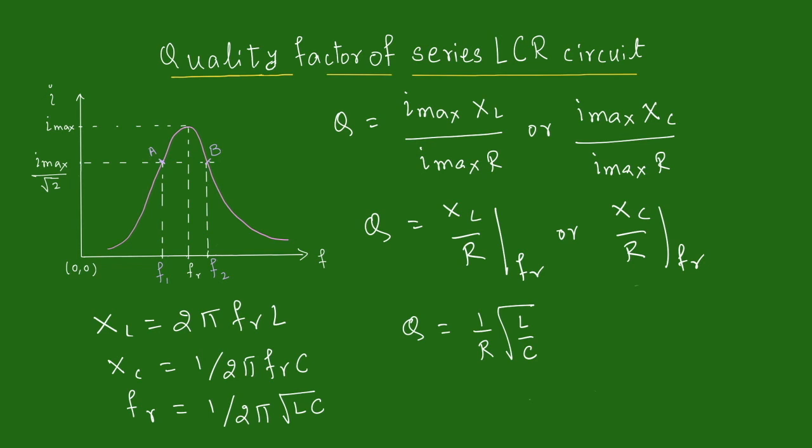that the quality factor of a series LCR circuit can be increased by using an inductor which has a high inductance value but low internal resistance. Quality factor of the series LCR circuit is also given as resonant frequency divided by bandwidth of the circuit. That means for the LCR series circuit to have a higher quality factor, the bandwidth of the circuit should be kept as low as possible. Larger quality factor also shows that the circuit has good selectivity for the resonant frequency.